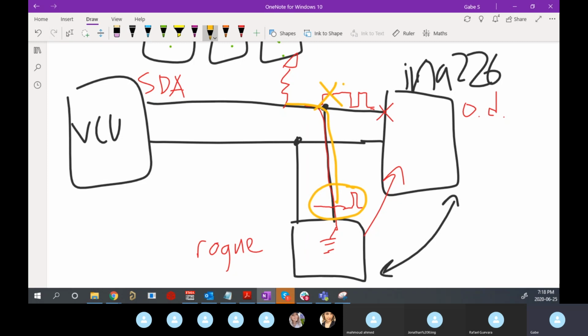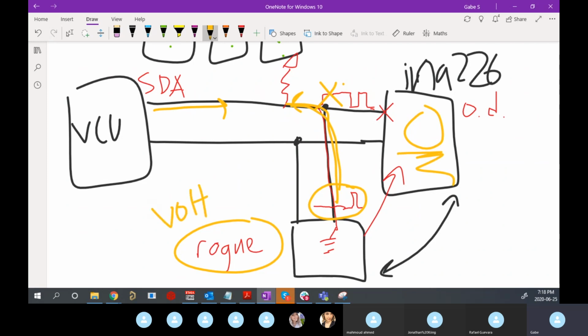So you have to be careful because you sent data, you're expecting to talk to the current sensor, but somehow you have a rogue sensor with the same address, and it's sending back its own agenda, right? So while you think you're getting data back from the current sensor, maybe you're getting data back from a voltage sensor or some other thing that has the same address by accident. And so who knows what's going to happen? Everything's going to be completely messed up. But that's sort of a thought experiment of how it would work.